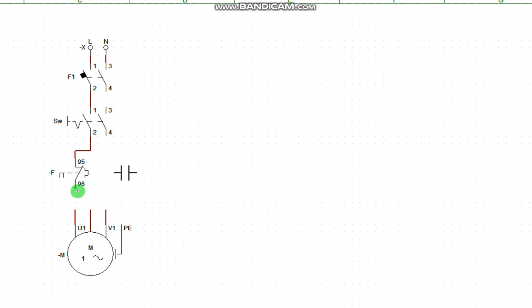Then from my overload, I supply the motor. That one has gone. So starting with the second line, neutral comes to the switch. From the switch, go to capacitor. Then from capacitor, you come out, you go to motor. All right. Then the capacitor permanent I told you about will now come out and go to capacitor this way.